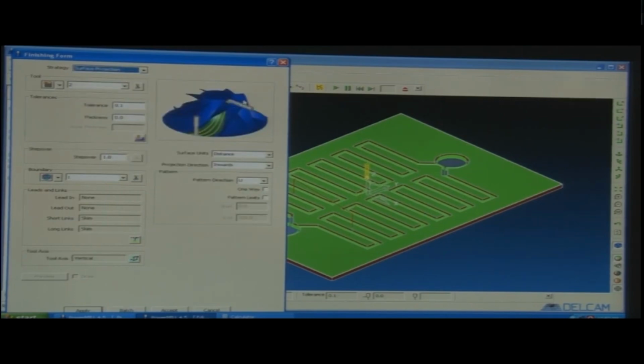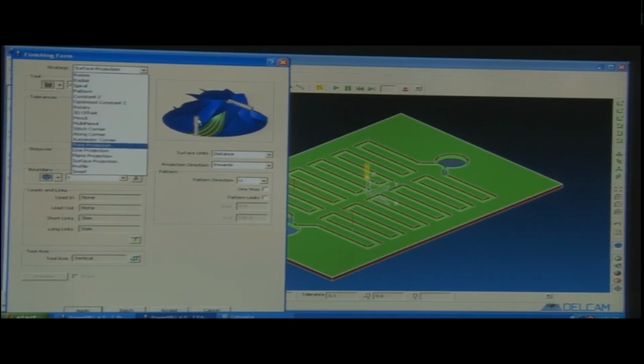Now, what is there? You can see the tool in 2 directions here. Here the tool is in horizontal direction and the tool is also in vertical direction. So, this is surface projection. How does surface projection happen? This can only happen when we have at least a 3 plus 1 axis machine. So, this is a kind of free form surface, with a 4 axis or 5 axis system. So, this is a vertical tool, this is a horizontal tool.